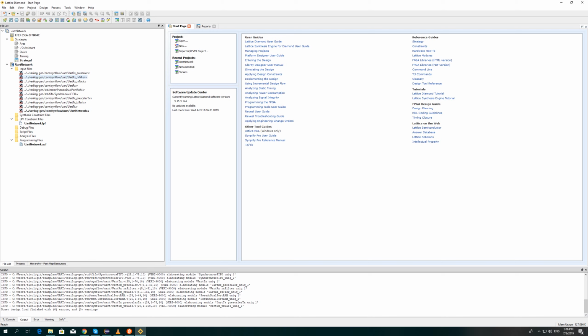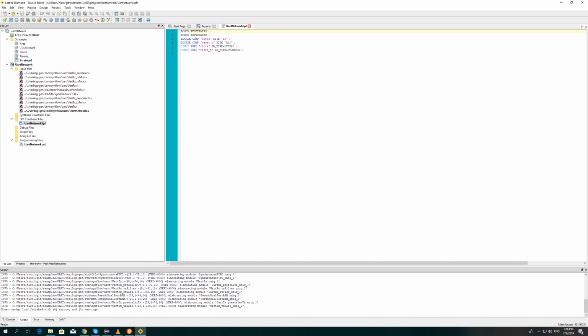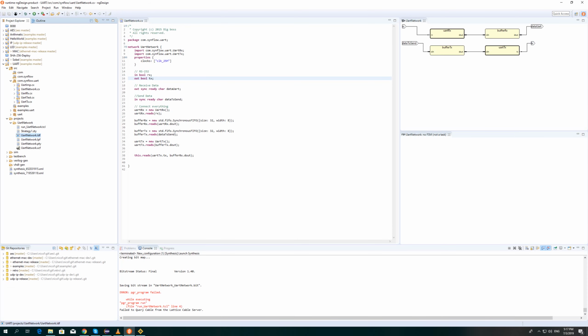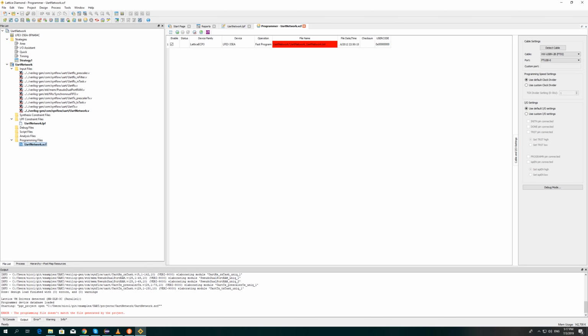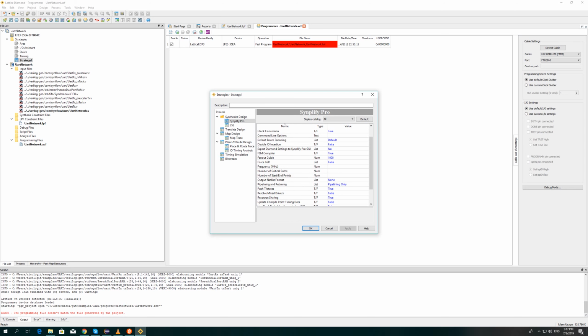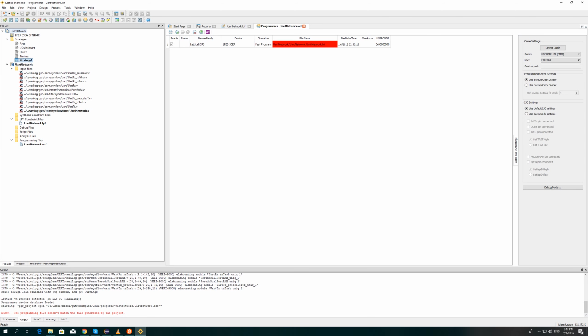And you can see in the generated project that you already have everything configured. So to modify the mapping, for example, in my case, clock reset on L5 A21, so that's correct. But I also need to add the TX and RX port. So I will modify that file to add a TX, RX and add a site. I can also modify the FPGA if I want, the device, or modify the strategy, and so on.